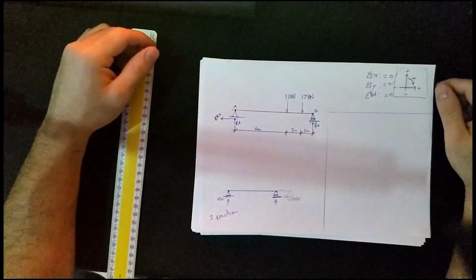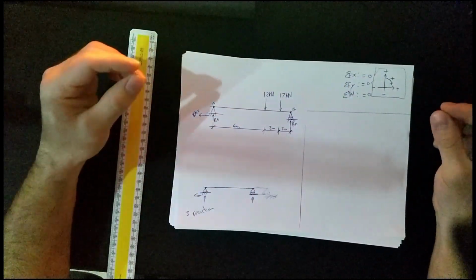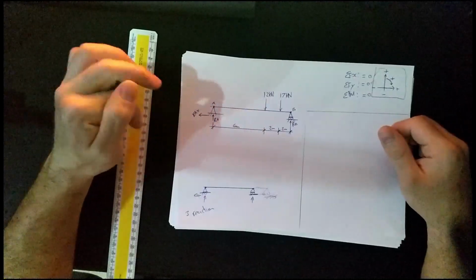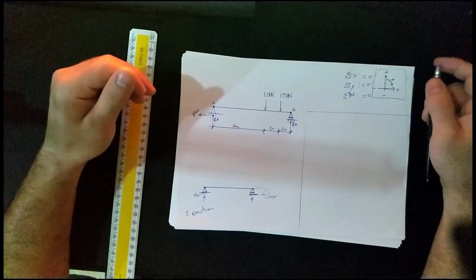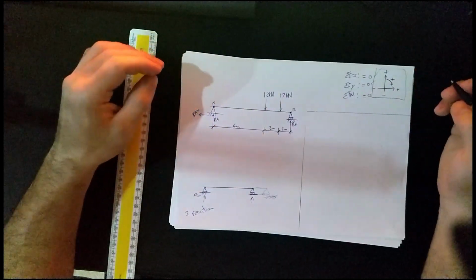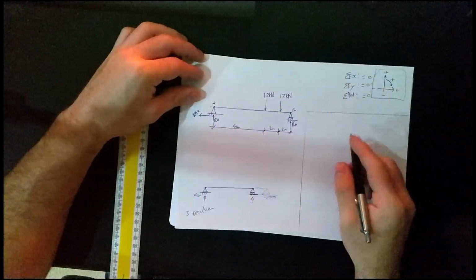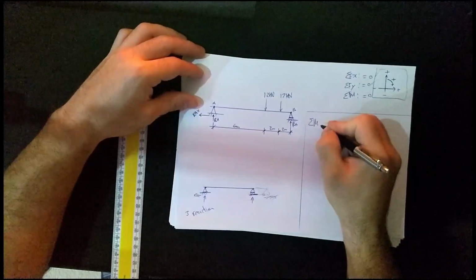First thing that we want to do to tackle this, now we've made all the assumptions, is taking moments from a point. We've got point A and point B, it's a very simple beam. So I'm going to go straight ahead and say we're taking moments at point A, which we write as sum of moments A